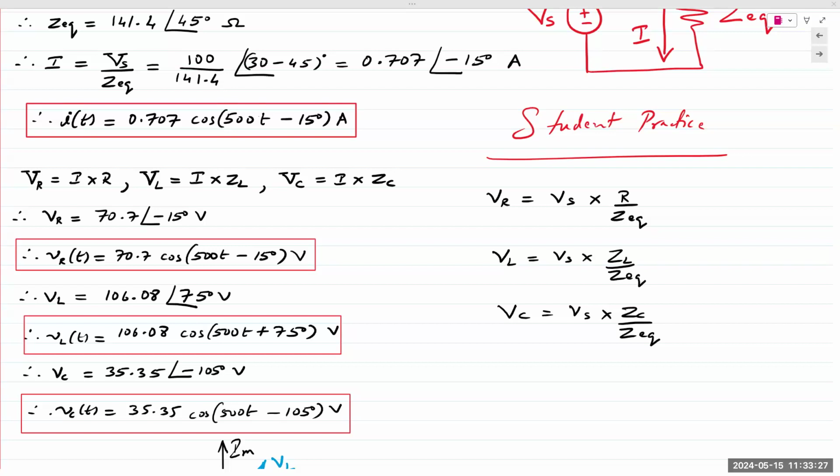The confusion arises from the fact that with AC itself, the voltage or current is always fluctuating, right? It does not stay steady with time. And the transient also, we say the same condition, meaning it's not steady with respect to time. So there's a conflict with those two. Am I understanding your question correctly? So it's two separate things. There's a transient response, which decays to zero after some point in time. And then what is left is just a steady state response. Now, the steady state response is also a function of time.